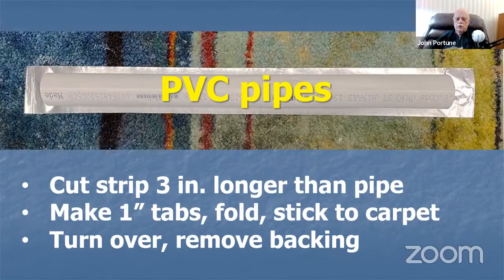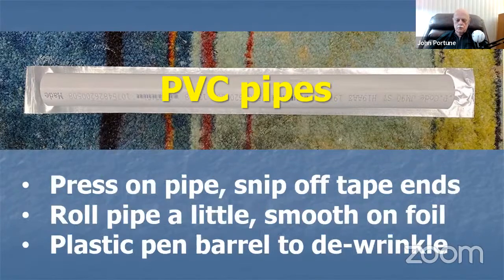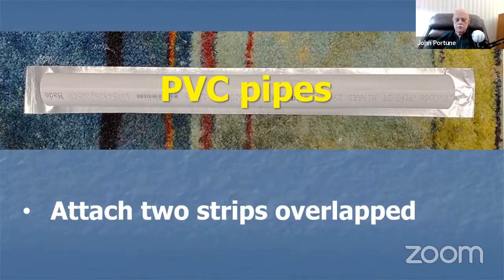The tape, by the way, because you see here, is applied longitudinally. You don't wrap it around the pipe. You put it lengthwise on the pipe. 2 overlapping lengths of 4-inch aluminum foil tape. And a little tricky, but this way it's easy. You can cut the ends off after you're done, roll it back and forth, and it sticks on nice and smoothly. So you press it on the pipe, snip off the ends, roll the pipe over, smooth out the foil with the barrel of a plastic pen. And you apply 2 strips overlapped.